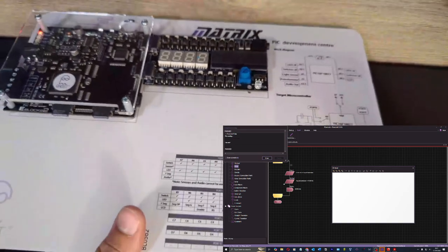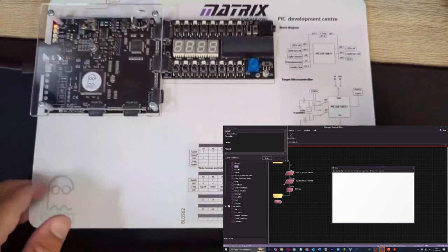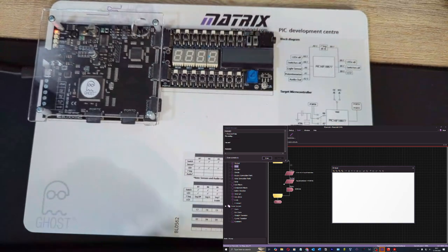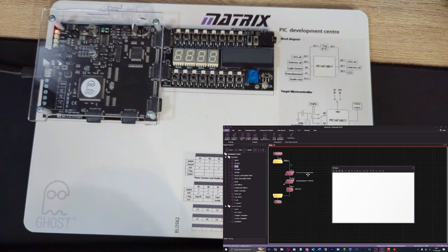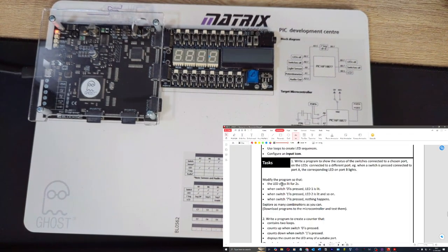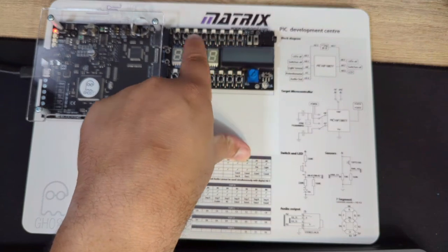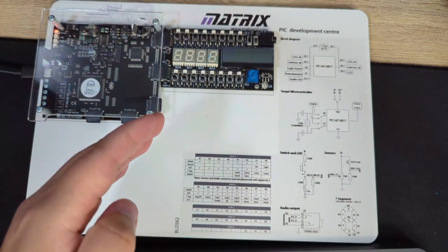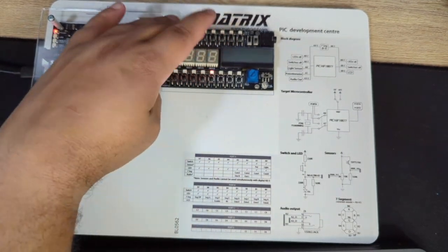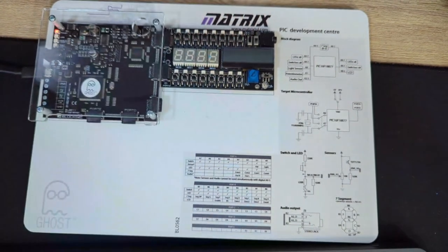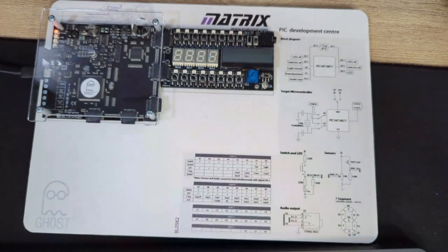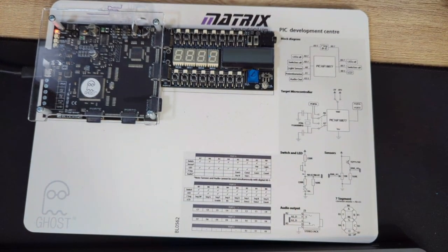So what I think about there is that this input switch needs to be like an interrupt, and not the way that I've done it. But that works, but not properly. And to me, this is an opportunity for them to actually teach about interrupts now, because that switch there, or any of these switches, for the purpose of what I want to use it for, should be a hardware interrupt, going onto an interrupt pin. But again, I digress.